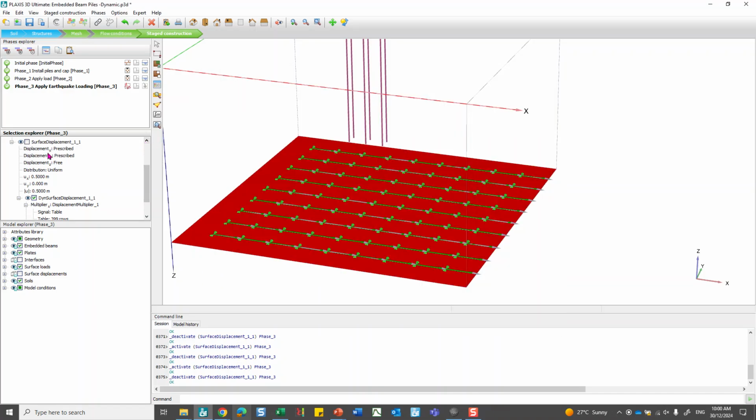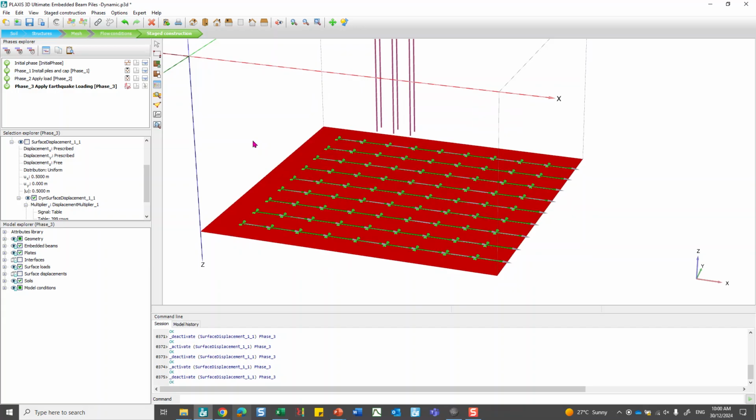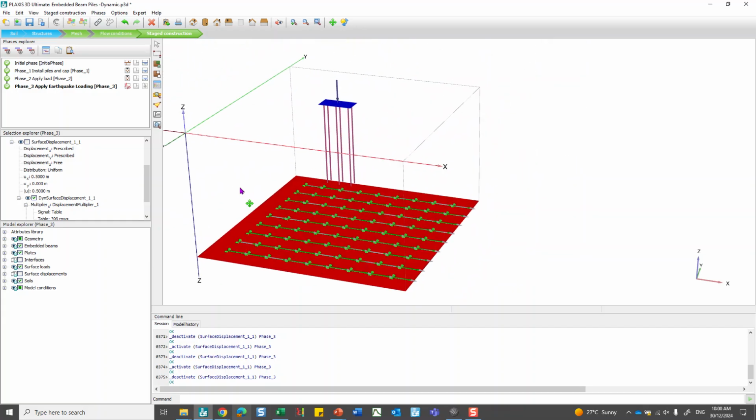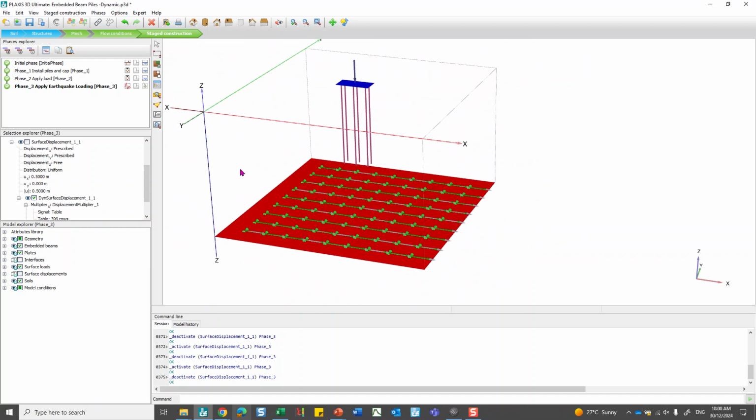It is essential here. This is a prescribed X, and it has to take 0.5. This is a requirement by PLAXIS to get the time history applied correctly and the corresponding response spectrum within the soil model and at the ground surface correctly. So this is more of the way it's calculating, because you will have bedrock below that surface here.